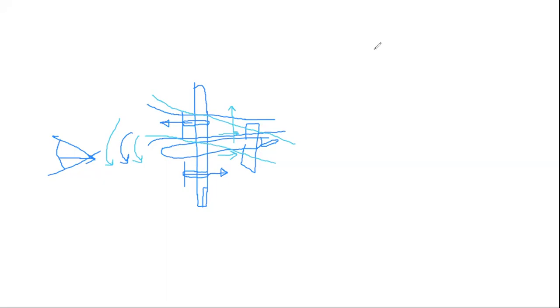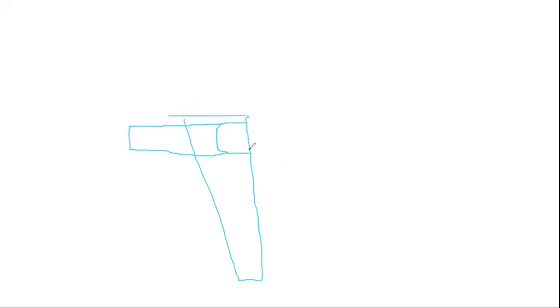Okay, about the AN-72. This extra lift depends on two factors. Firstly, it depends on how much area of the wing is immersed in the jet stream. So in the case of the AN-72, we have only a very small part of the wing.